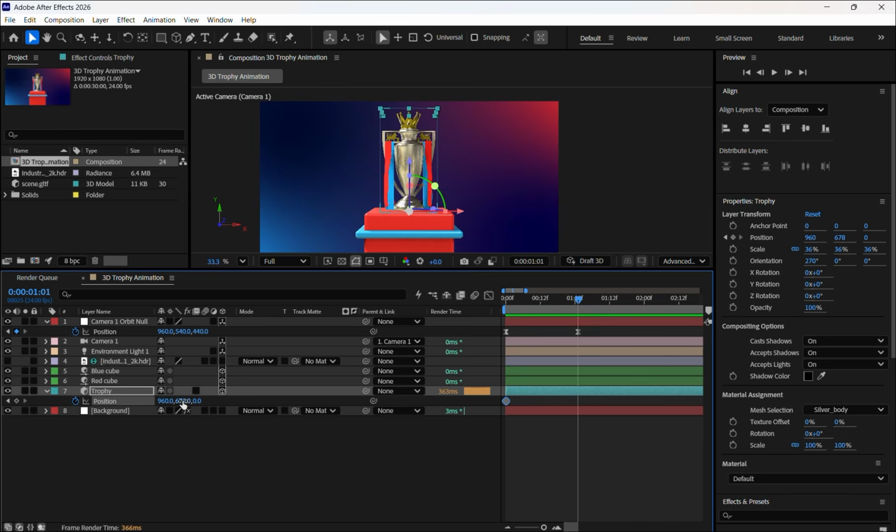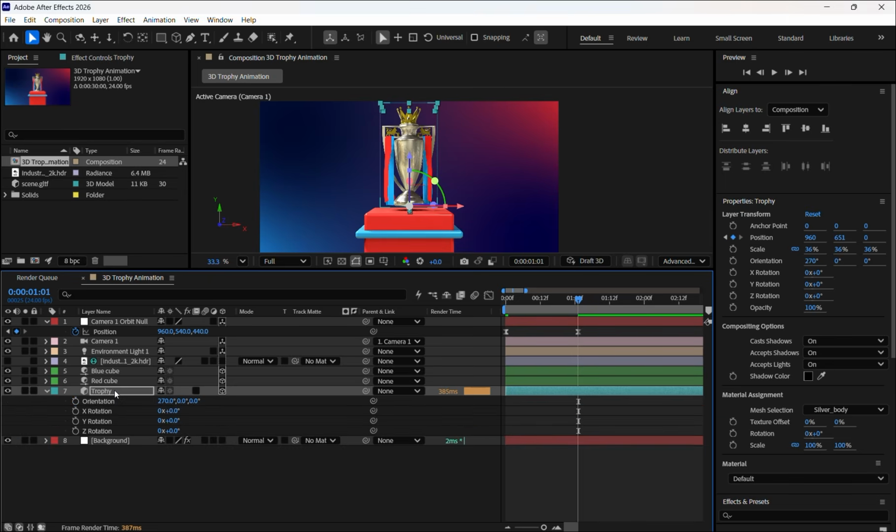move this X. Now we are moving Y axis, so let's move Y axis slightly on top. Yeah, this much is fine. And also let's rotate it. So press R, that will open the rotation details. And now we can check here whether this is not the rotation that we want. Let's see X axis. This is also not the rotation that we want. So now this is the rotation that we need. So here we'll use Z rotation.